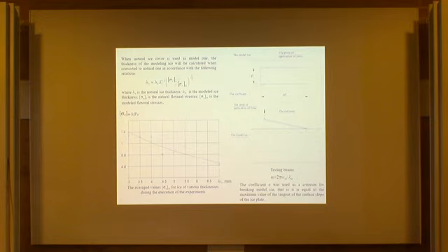The coefficient alpha was used as a criterion for breaking model ice. That is equal to the maximum value of the tangent of the surface slope of the ice plate. The relation between failure of ice cover and the coefficient alpha was already empirically determined in Skozin's experimental work.